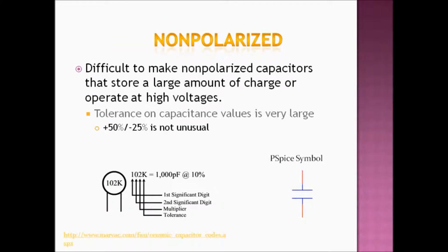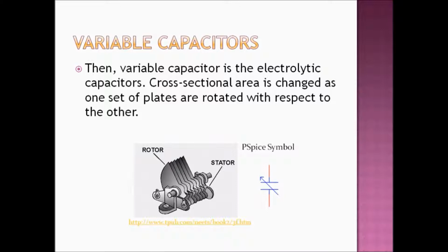Non-polarized. Difficult to make non-polarized capacitors that store a large amount of charge or operate at high voltages. Tolerance on capacitance values is very large. Plus or minus 50%/25% is not unusual. Variable capacitors.